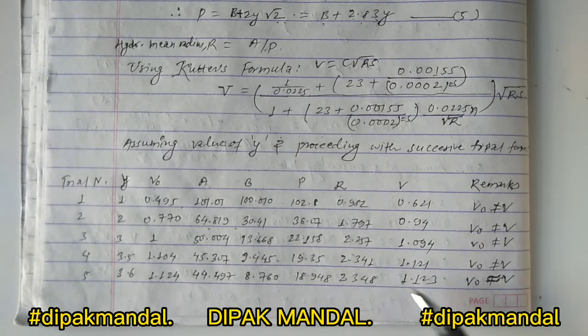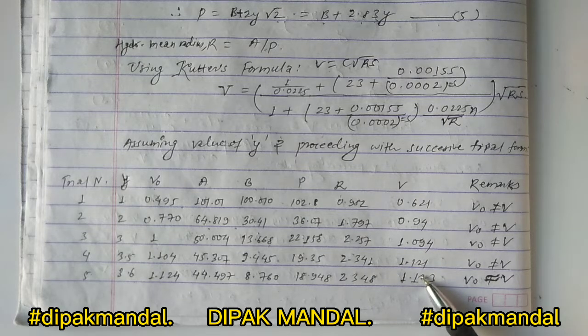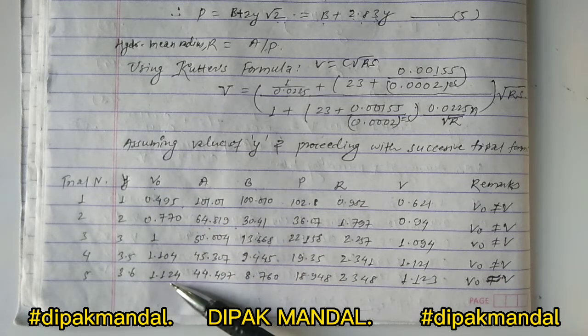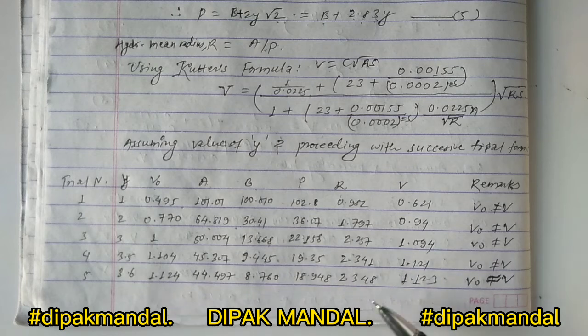So you can see here in this trial the actual velocity equal to 1.12, and critical velocity is also 1.12. So these two values are very nearly equal, and the remarks become V naught is nearly equal to V. That's why we stop now, performing the next trial.